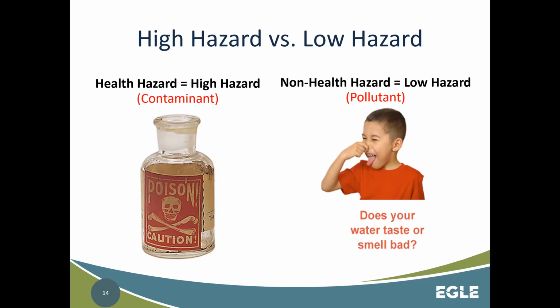It definitely doesn't look good because it leaves rust stains on stuff. But we consider something like iron a low health hazard because it doesn't hurt anything. It doesn't look good and doesn't taste good. But in the grand scheme of things, there's no known health risk with ingesting iron in well water. So that's why it's considered a low hazard.